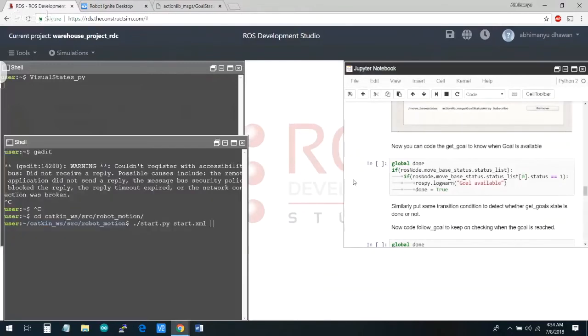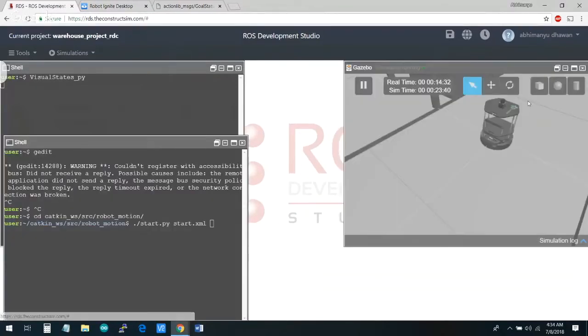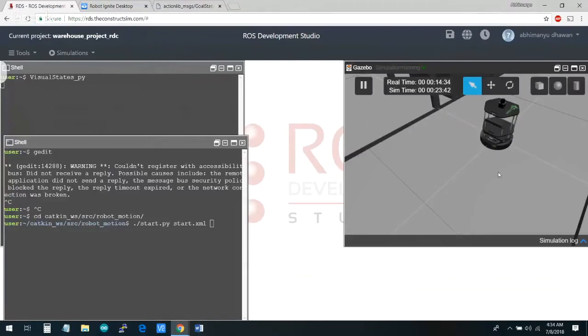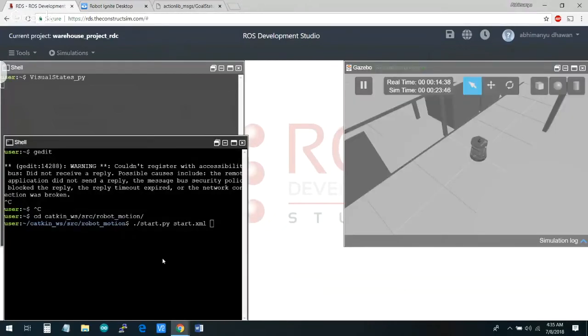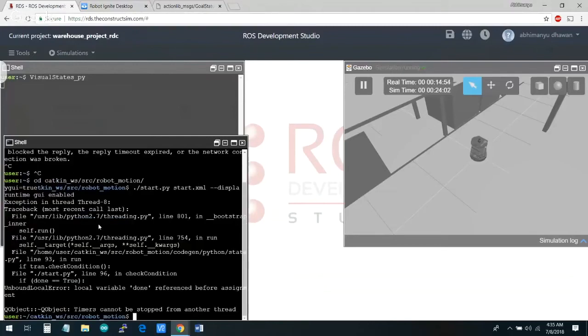Yeah, basically you must have it in Gazebo first. Don't forget to open Gazebo with the launch file, so it can find the robot which you are trying to use. Don't worry, the overwriting is fine. It's a bug.